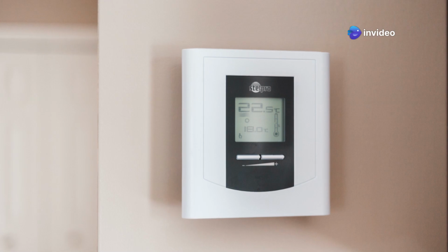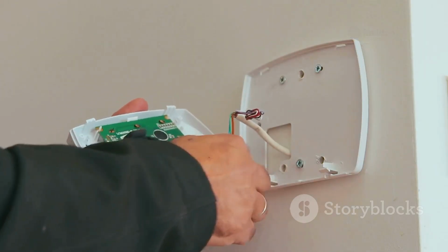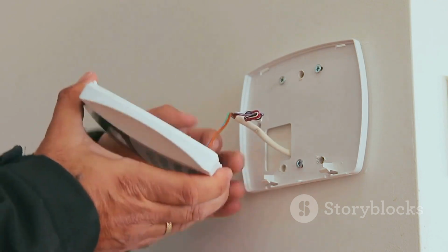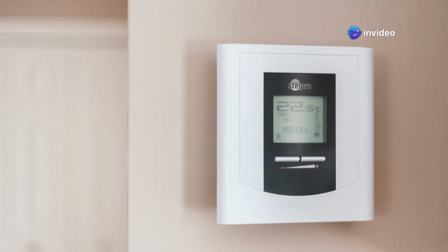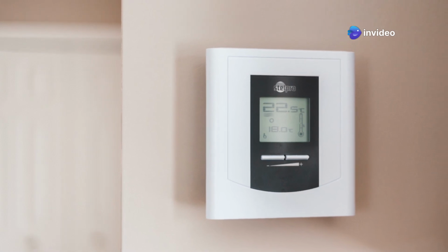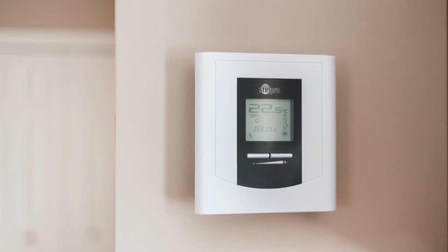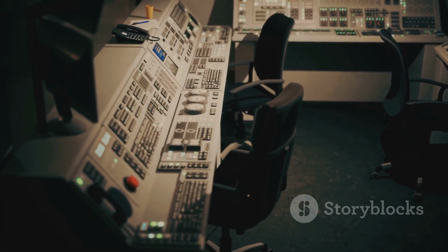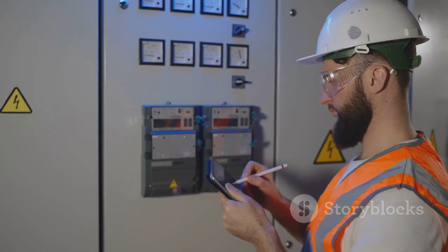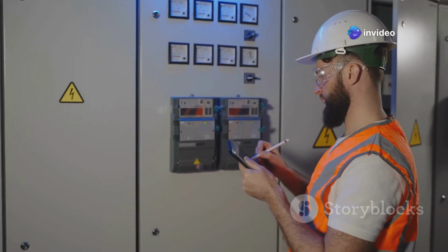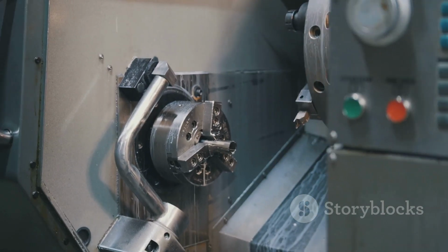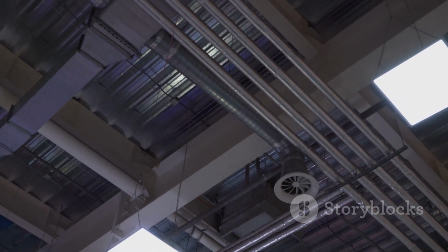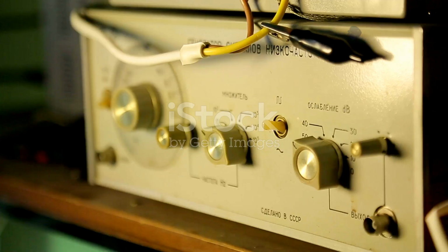But why is this important? Well, imagine trying to control the temperature in a room. The 0-10V signal can tell a thermostat to gradually increase the heat, while a 4-20 mA signal can do the same but more reliably over long distances. The RTD can then provide accurate temperature feedback to ensure the room stays comfortable. These signals work together to create a seamless, automated environment. In essence, mastering these signals is the foundation of any smart building system. They are the unsung heroes that make modern conveniences possible. Now let's move on to see how buildings themselves communicate through these signals.